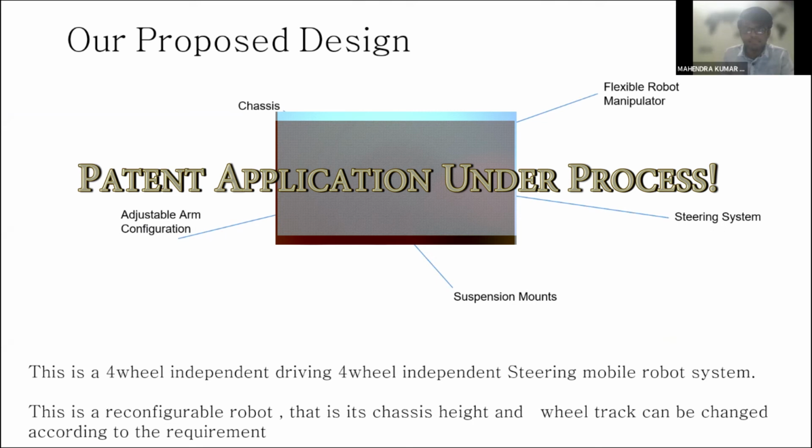As you can see here, this flexible shoulder is there. In this mechanism, we can rotate this arm, and we adjust the height of the robot. There is a lock, and you manually rotate the link. As you can see the shoulder here, we can loosen the screw, and we rotate this 4-bar mechanism here, and we adjust the height and lock it there. This way we adjust the height of the robot.